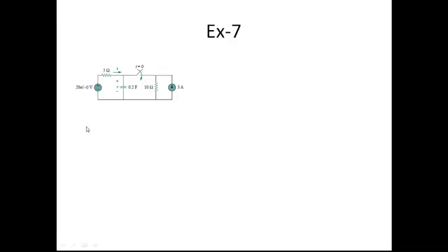So you are going to draw two circuits. One is t lesser than 0. Another one is t greater than 0. For t lesser than 0, what will happen? This source will be present because u of minus t takes the value 1 for t lesser than 0, whereas the switch is open. So this particular portion will not be there. So for t lesser than 0, your circuit is like this: 20 volts, 5 ohms, 0.2 farad. Your circuit is very simple like this.